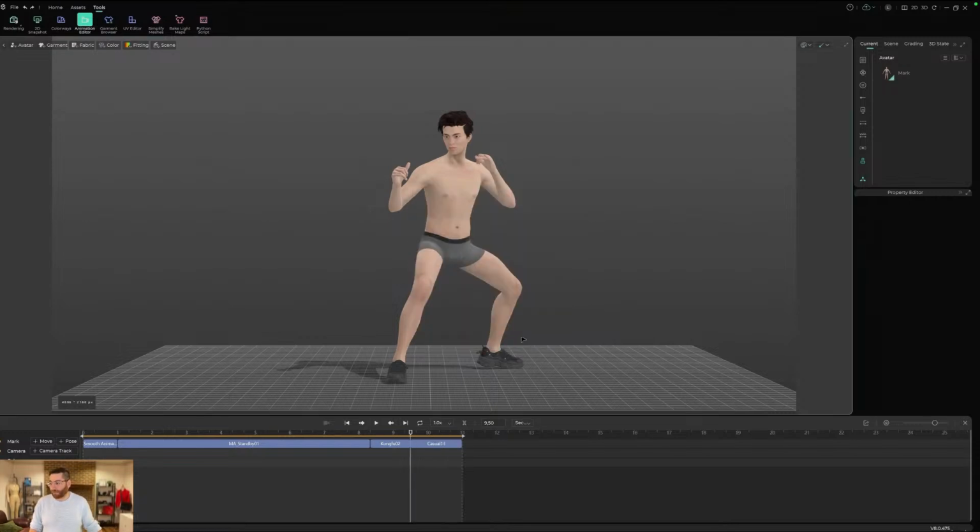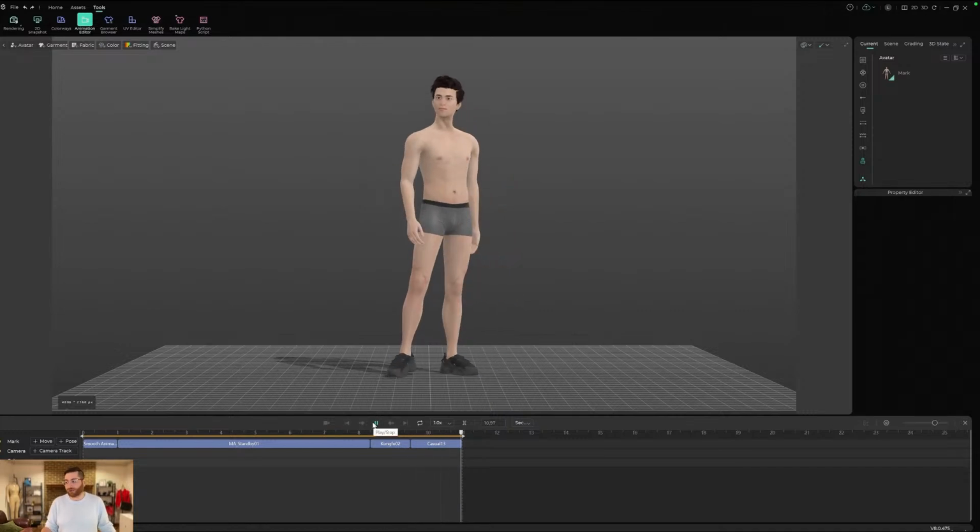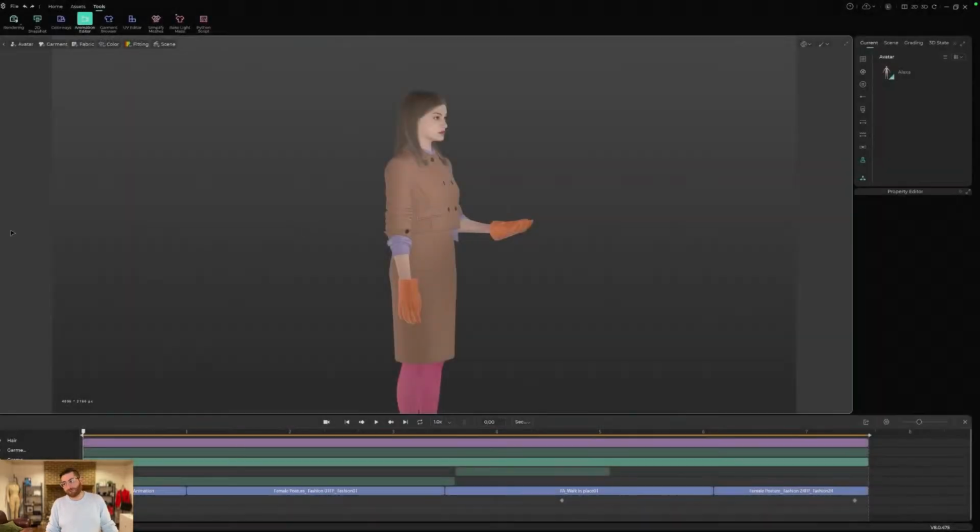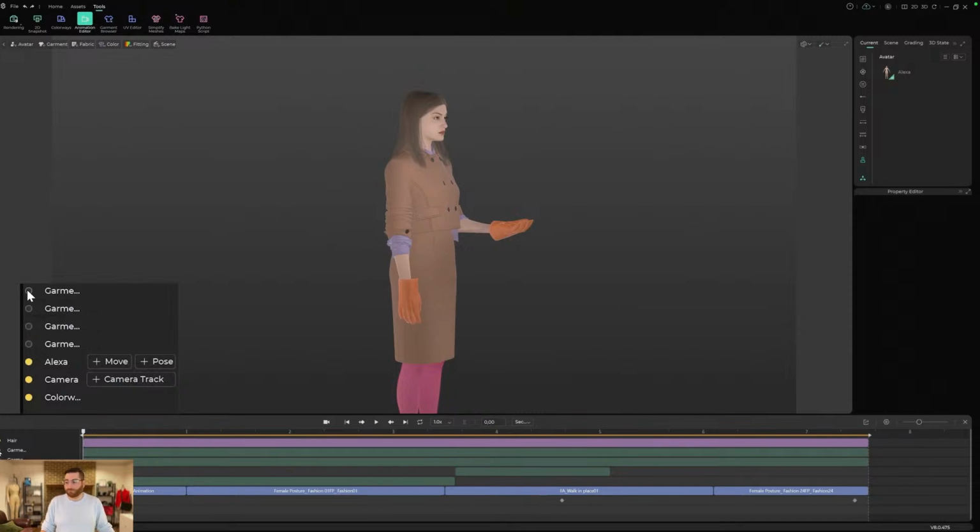And we get this option to add in a 1 second or shorter or longer automatic transition animation that gets created by Style3D automatically. Very, very useful for even beginners trying to use animation in Studio. Here you can now enable and disable individual garment components from the timeline view. So you can tick these timelines on and off.